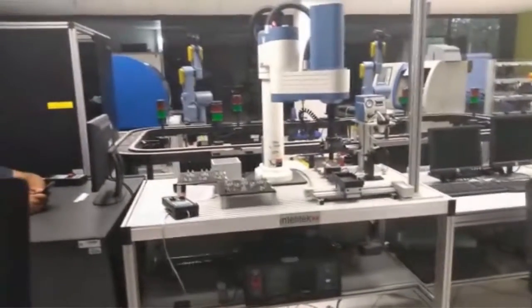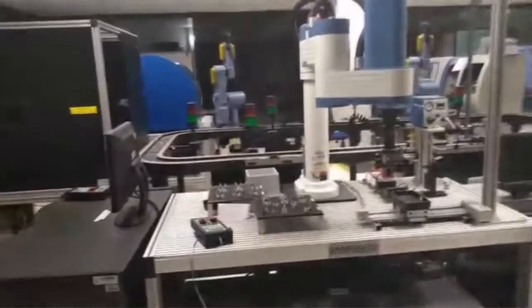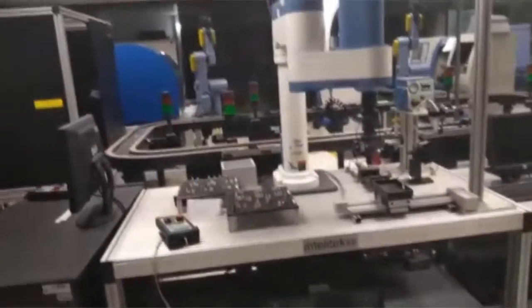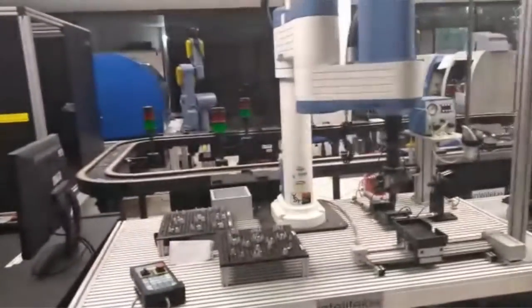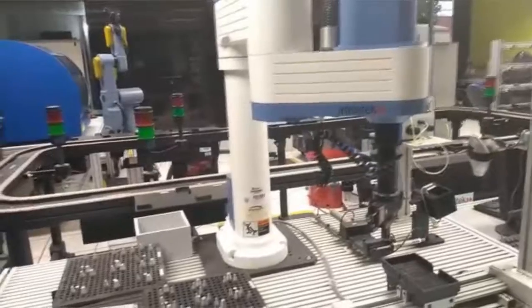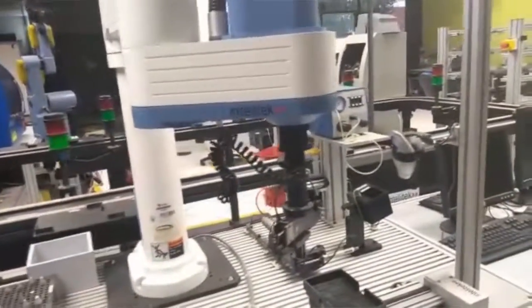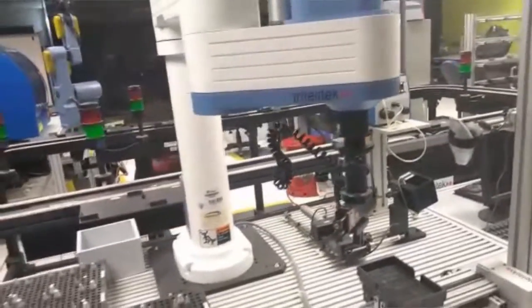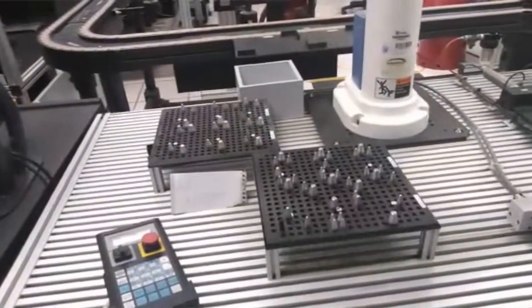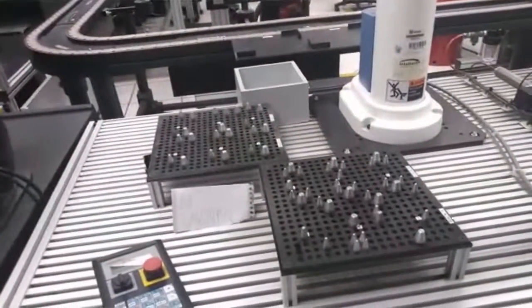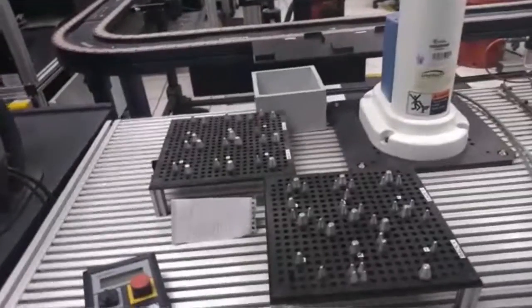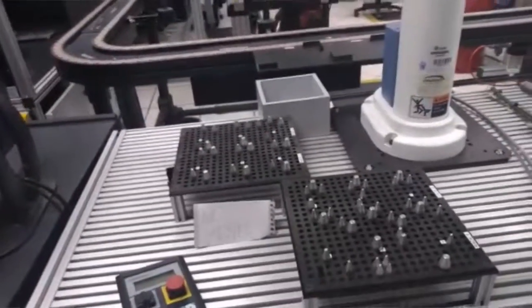Workstation number 5 has a SCARA type robot with 4 degrees of freedom, which can make movements in the plane for assembly operation or operation of a specific process. In this case, it performs 2 processes, the assembly operation and the visual inspection operation, that is quality control. It has temporary racks with defined space that serve to temporarily place parts so that they can be assembled.